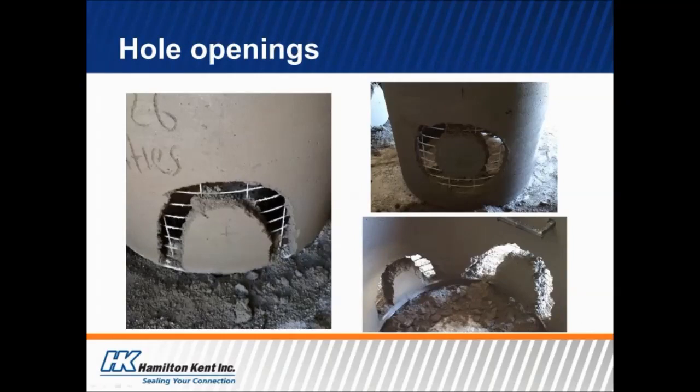This is another method I've seen, and this is at a dry cast plant, and this is how they were setting up for openings for the job site. This process is labor intensive, as each of these openings is created by someone basically poking the concrete away from that wire mesh in the dimensions that are required for that job or for that project. It also wastes a lot of concrete and requires a lot of cleanup. So, in my opinion, not a very efficient method either.